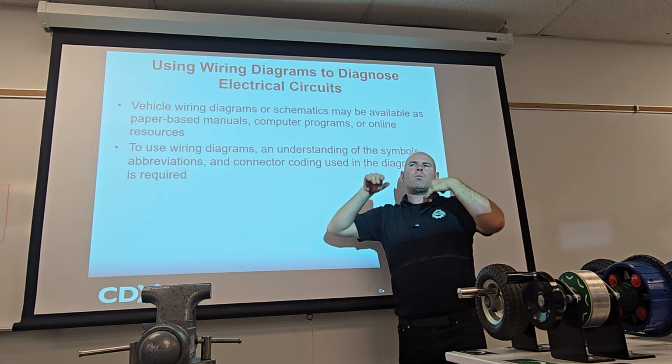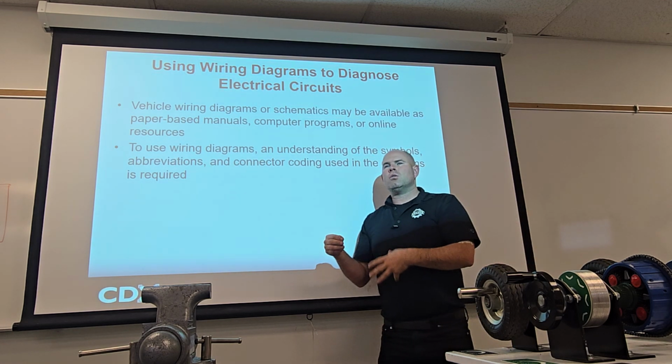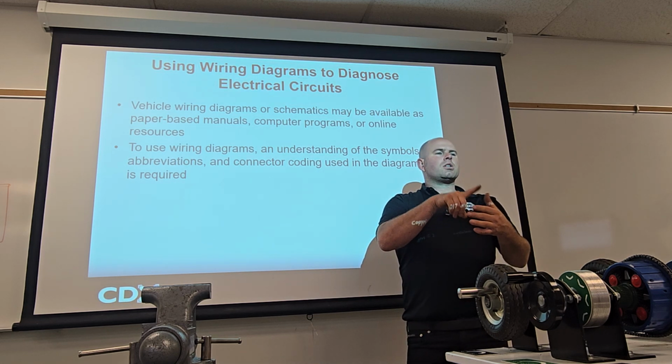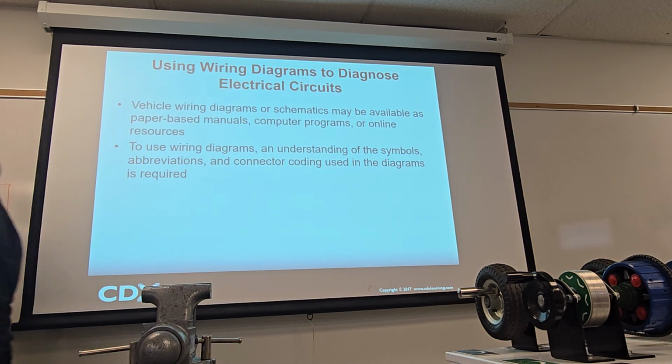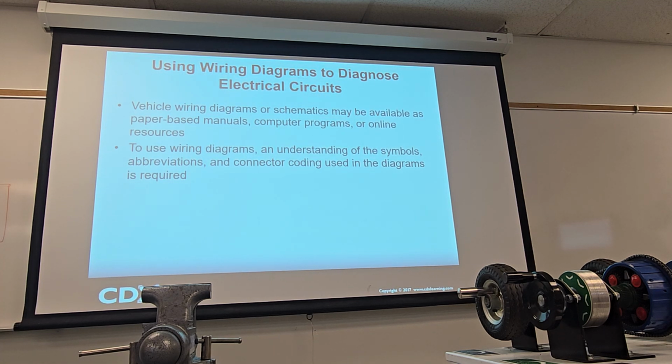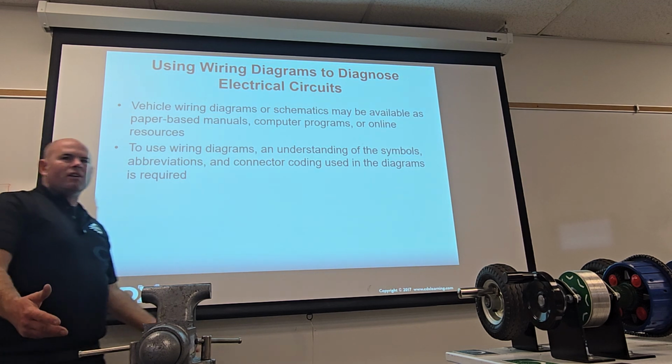And if I really wanted to diagnose that, the way I would do it is check the available voltage to the circuit board. And how much should it have available to the LED, would you think? Talking about a load, right? How much typically would a load have if it's a taillight? Should have 12 available, right?